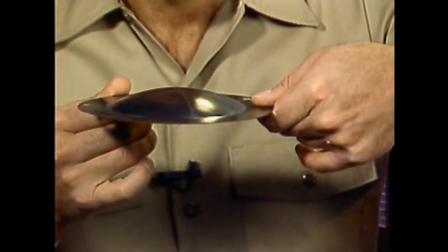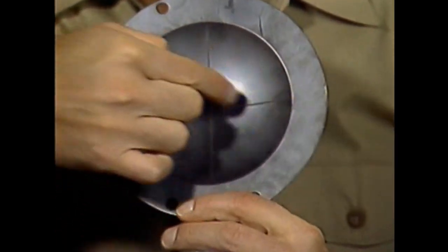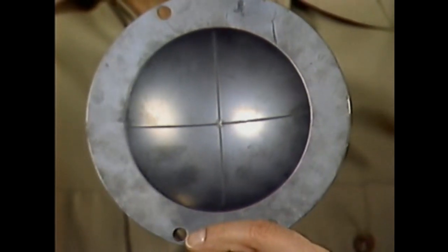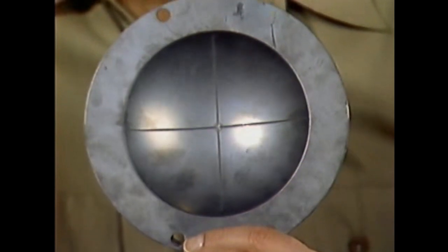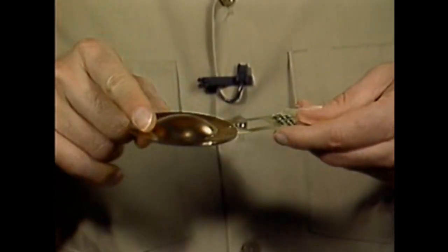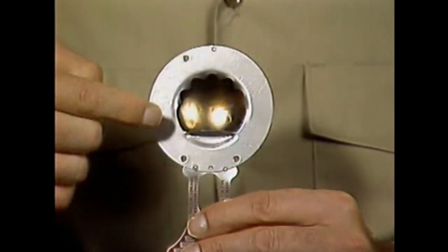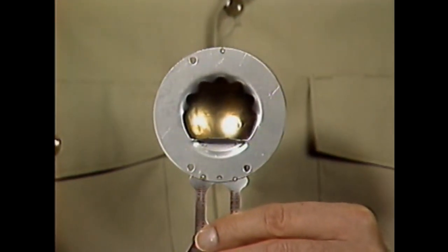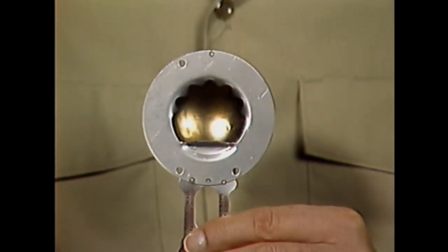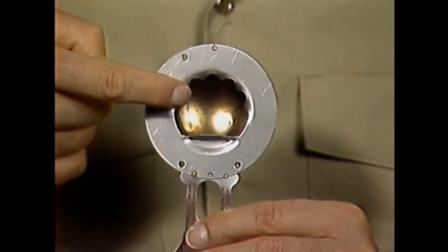Here are some examples of typical rupture discs. This one is dome-shaped. The lines on the disc are really small cuts in the metal called scoring. The disc is designed to split at the scoring lines at a certain pressure. This rupture disc is also dome-shaped, but it has a plate with a jagged edge located behind the disc. When the dome begins to buckle in response to excess pressure, the jagged edge cuts into the dome and helps